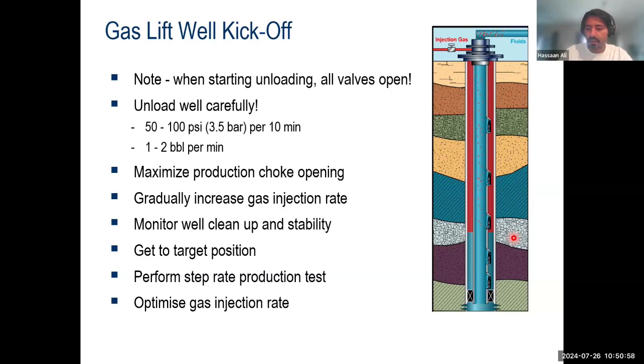The reason for that is that one of the things that you need for gas lift is a gas compressor. So you need to have a gas compressor, or a space for a gas compressor, in your offshore platform. And the people who have actually worked on an offshore platform can tell you that space is at a premium. So if you deployed an offshore platform without a gas compressor and all the other equipment that is required on the surface for the gas lift system, and later in the life cycle of the well you decide to deploy gas lift, you are going to face a lot of challenges because you do not have space for the gas compressor. That is one of the biggest constraints which I see. So early planning is very important, especially for the offshore field.